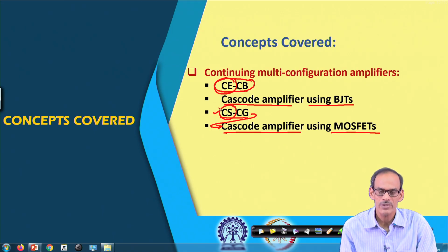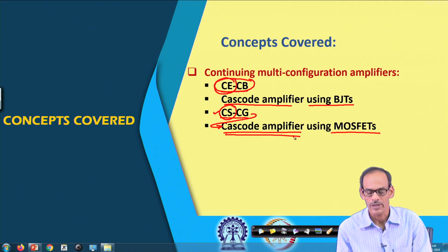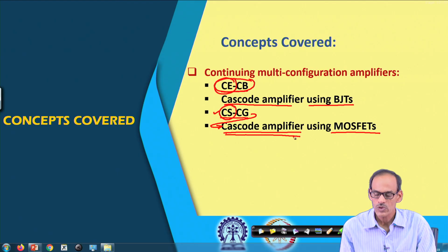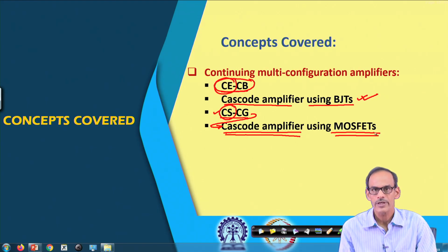So, we must have some alternative, particularly for the MOSFET version, otherwise that circuit may not be of much use. The cascode amplifier is one configuration in MOSFET amplifiers that helps to get higher gain. It may not be very popular in the domain of BJT amplifiers, but it is quite popular in the MOSFET community. Anyway, both circuits we will be discussing.